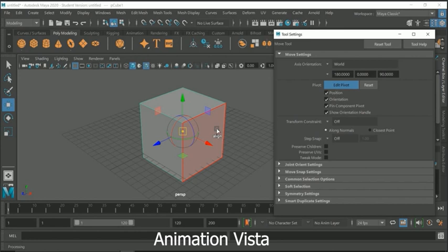What this does is, if we click on the edge, or surface, or corner, it allows us to align the pivot to the position and orientation of the selected edge, corner, or the surface. Alright? Now generally, we don't require to change the orientation of pivot, but we do require changing the position of the pivot a lot. Hence, we can uncheck this checkbox for orientation if we don't need to change it.